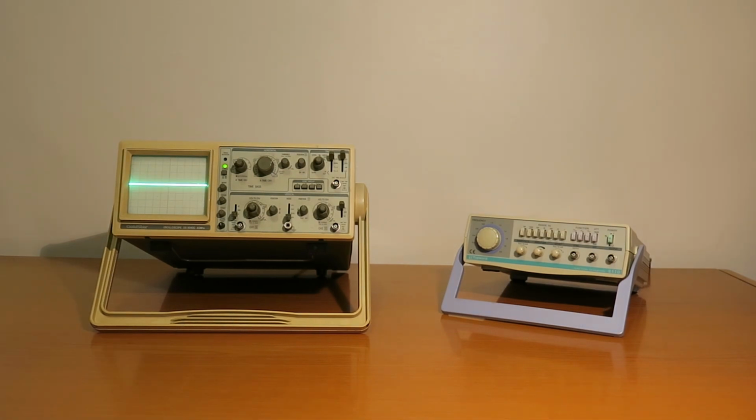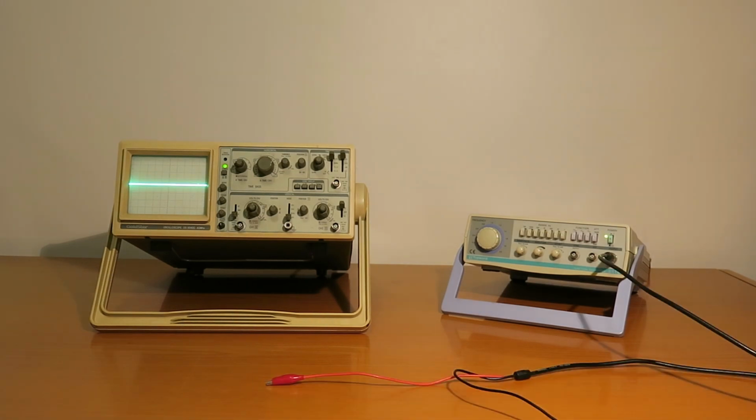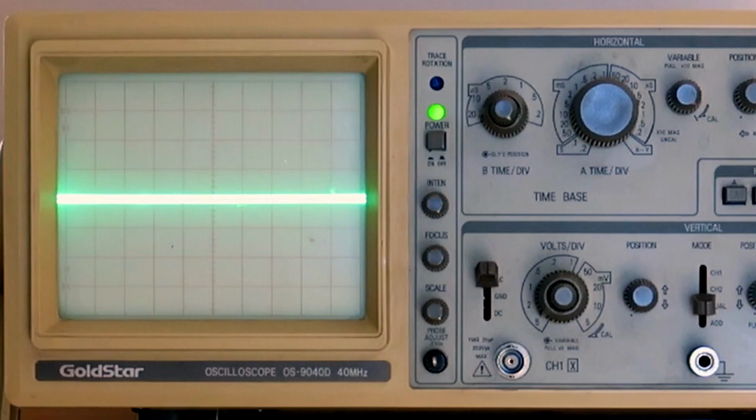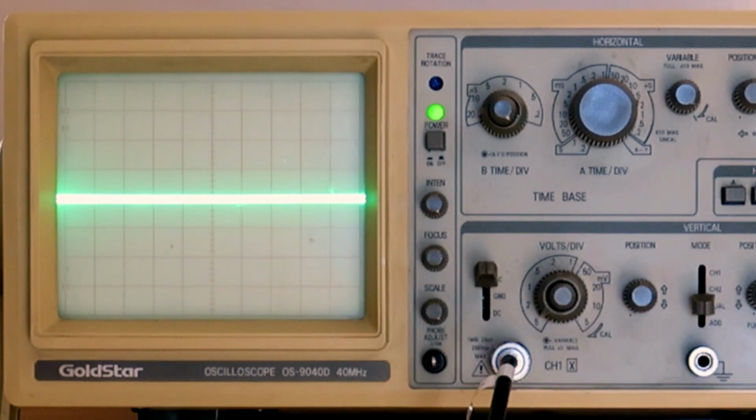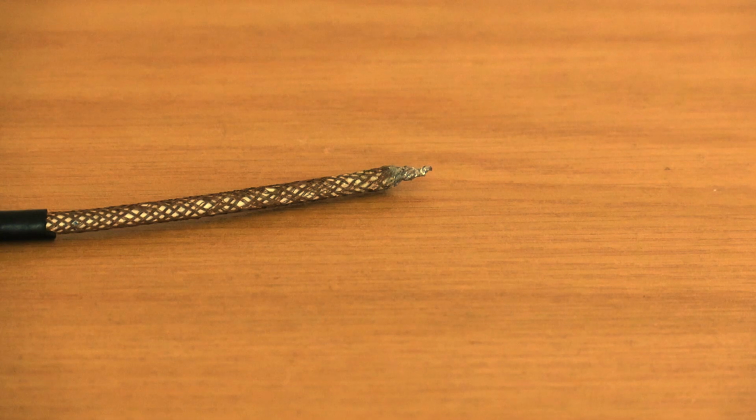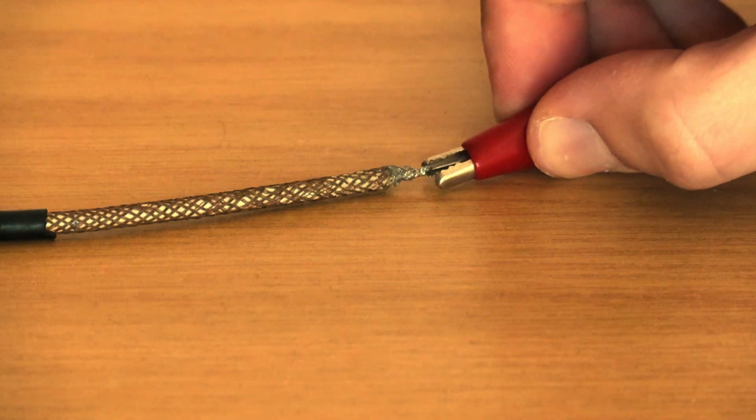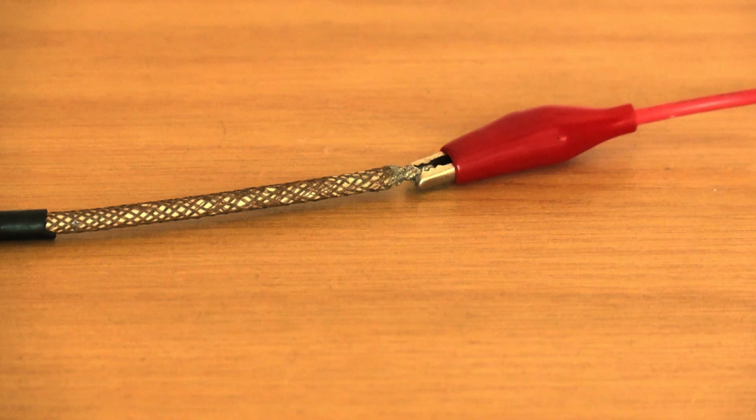At the signal generator end, the BNC to crocodile clip is connected. At the oscilloscope end, one side of the cable under test is connected. Remember, at the other end of this cable, the connector has been removed and the center conductor and the return conductor have been soldered together. The positive crocodile clip is then connected to the soldered together end.